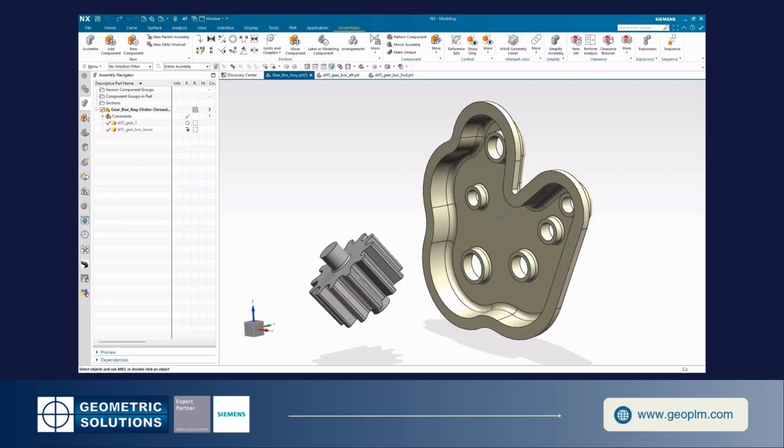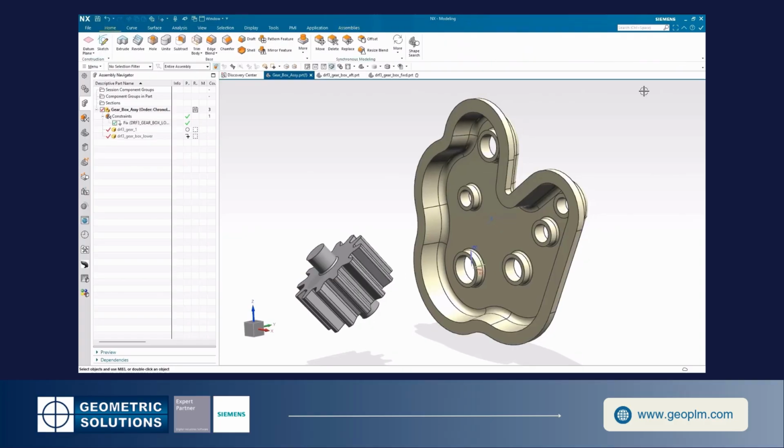Today, I'll share with you some of the new functionality that was released in NX 2412 and made available to our customers back in December of 2024. Key improvements are that NX will retain constraints as users restructure components within an assembly, and when they use copy and paste components, NX will include associative constraints. New capabilities are constraints, joints, and couplers for joints, both internal and external references. NX will either automatically update the external constraints to reflect a new position within the assembly, or provide an automated way to resolve these constraints as they're external to the paste function.